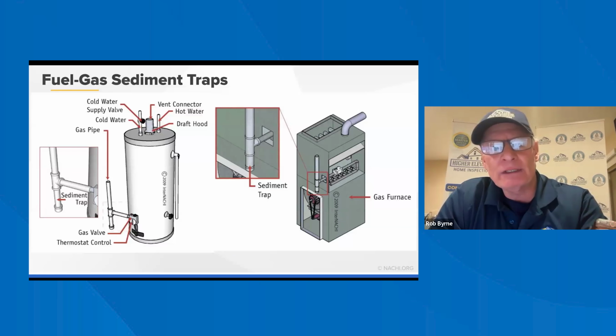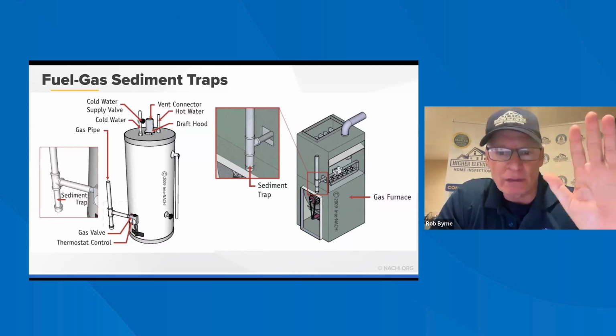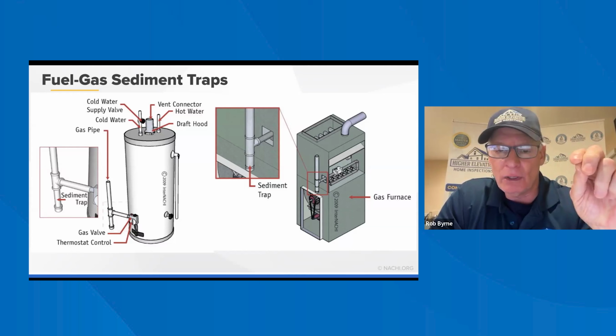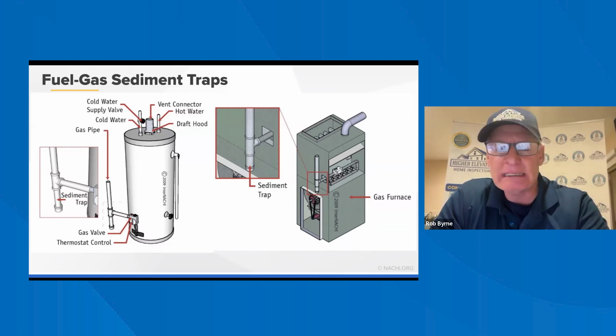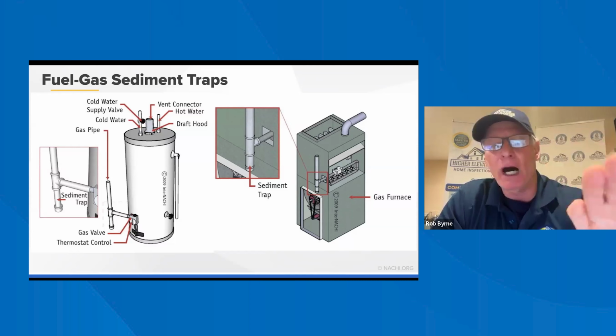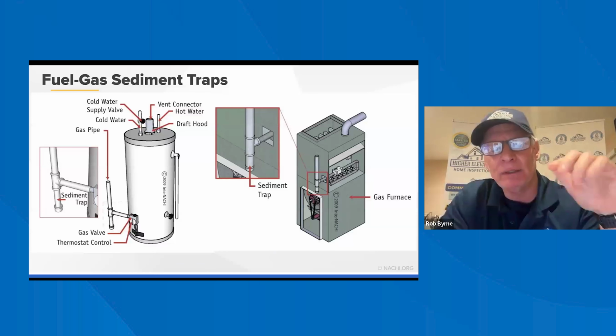When you're doing an inspection on this, be sure that you're looking at the pitch of that pipe, because unlike the waste line, where if it's not pitched properly things are going to back up because it's solid waste on the sewer line, now you're dealing with gas. You're dealing with a poisonous gas that is always supposed to be sloping up. So carry a little level with you, put it on there, take a picture, show it's not level, point it out to your clients.